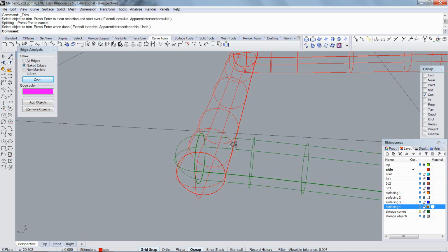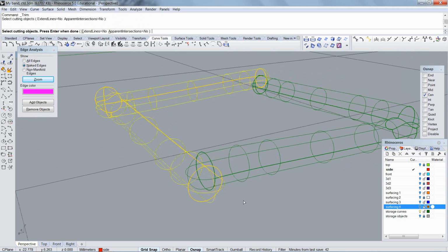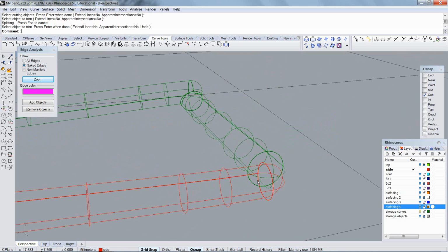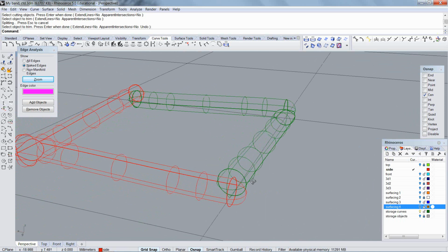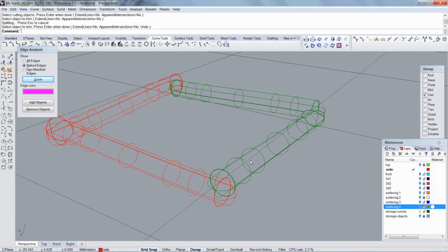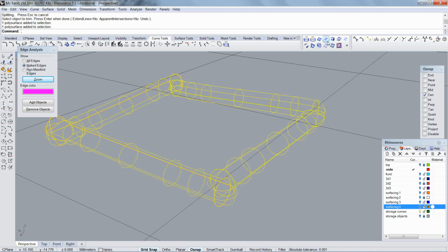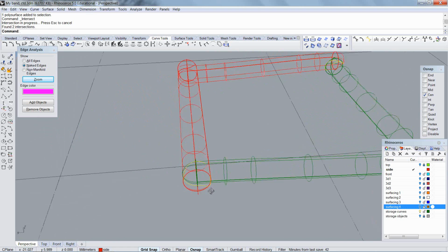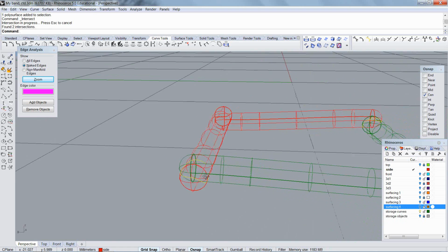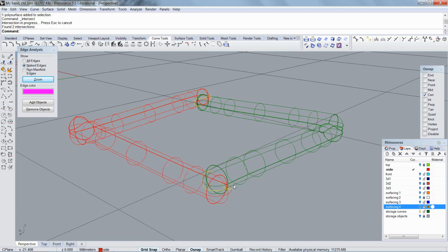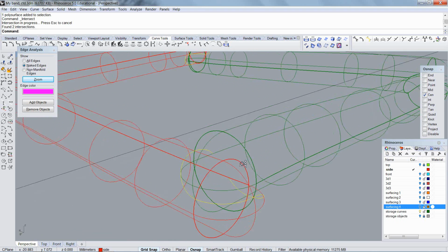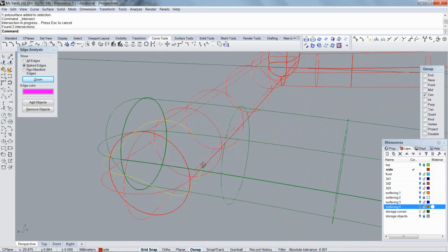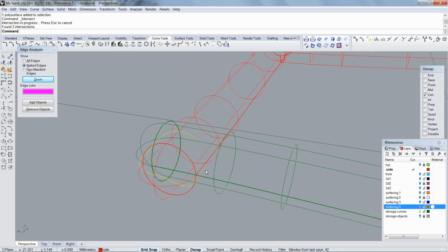No. When Rhino says no, it begins to become a problem. No. Okay? I'm not surprised, things like this happen all the time. Intersection. And there you see the problem. Are either one of those a closed curve? They're not. And a closed curve is what is needed to trim.